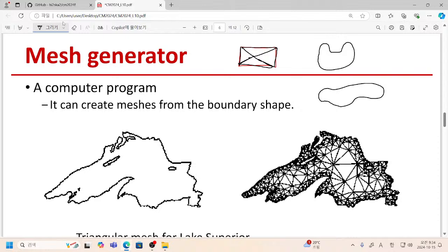So this is related to a problem called mesh generation. For a given boundary of our region of interest, how can we introduce a set of triangles or a set of tetrahedrons completely covering the simulation domain? That is really a big problem. Not only in computational microelectronics, every kind of computer simulation or even animation is much interested in this mesh generation.